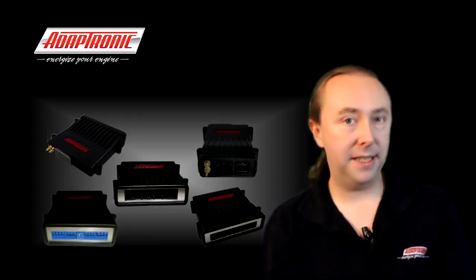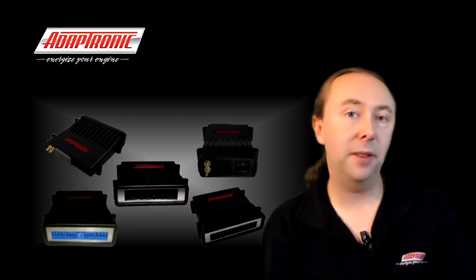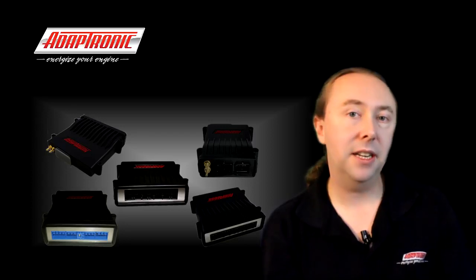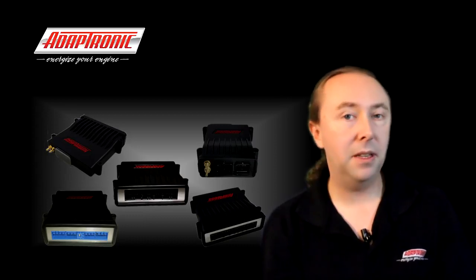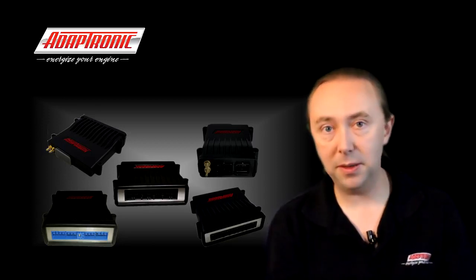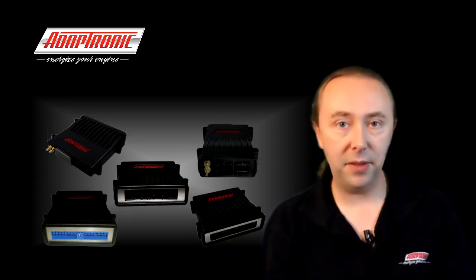Now let's talk about the most basic system, which is a single port actuator. In this system, the single port is fed with pressure from the boosted air exiting the compressor, and once that pressure exceeds the amount that's required to overcome the preload of the spring, the rod starts to move and the flap door opens. Now when the door starts to open, exhaust gas starts to bypass the turbine, and the turbo then has a bit less pressure available with which to build more boost. So it ends up in a position where it regulates its own boost in that way.